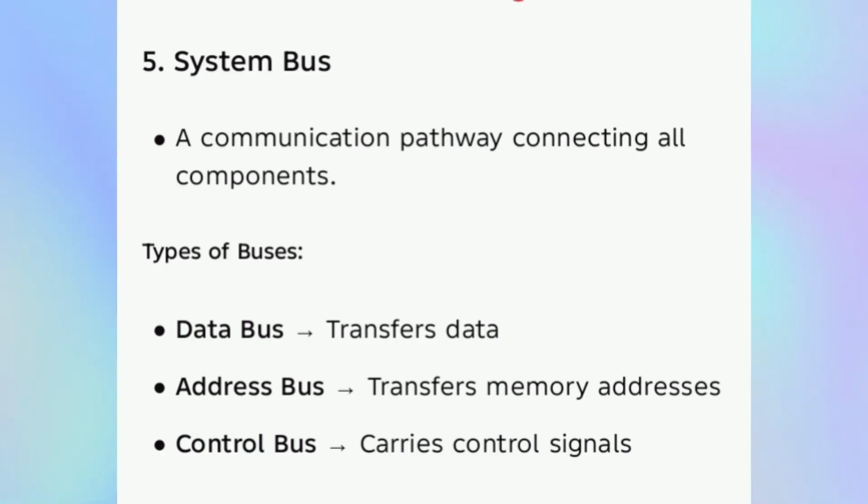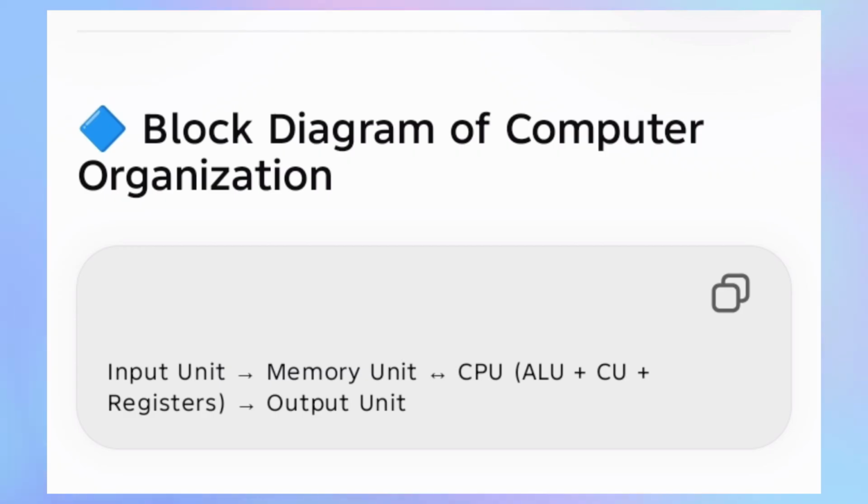The bus has three types. One is the data bus, another the address bus, and another the instruction or control bus. Each is a separate bus: the control signals have a separate bus, the address has a separate bus, and the data also has a separate bus. The width depends on how many bits the processor is capable of transferring.